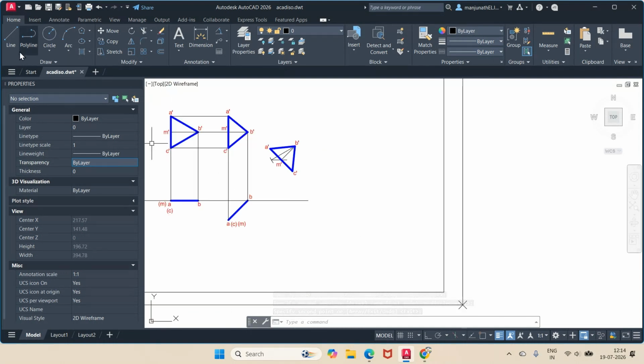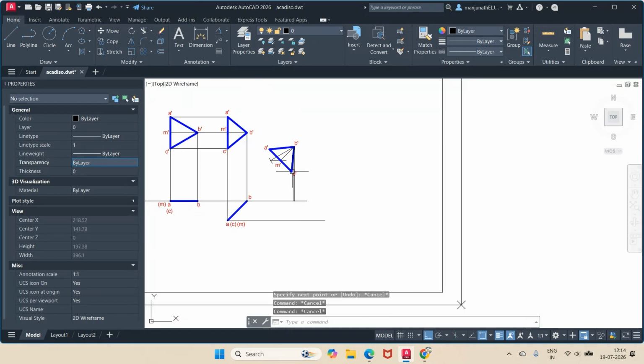Now I will take line and you enable this remove endpoint. I'll go for line, select this line and keep the ortho on. Now you go for trim, select this one. Similarly, I want to go for line, you select this from intersection. Then I want A and C now. So I will go for line, select this intersection, and now you go for intersection.